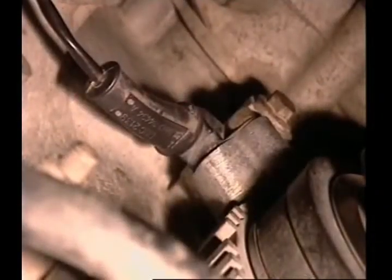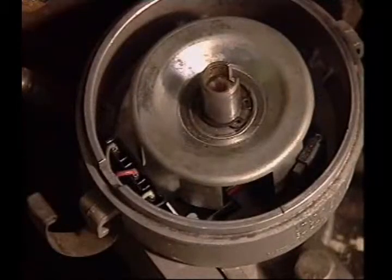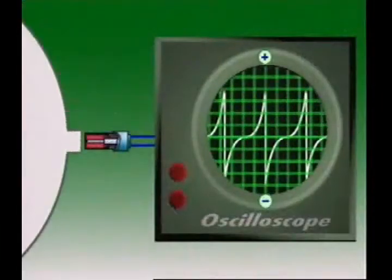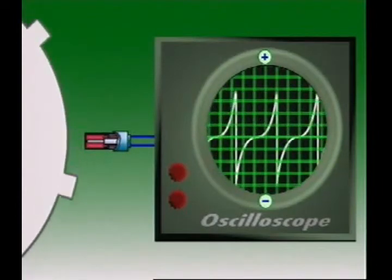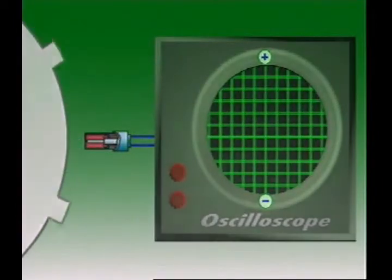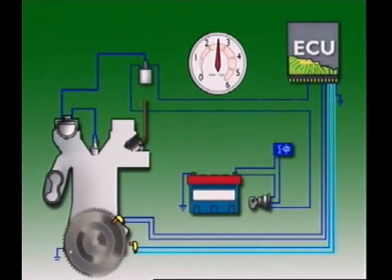The position sensor may be mounted externally on the crankcase wall, or it may be inside the housing of the ignition distributor. Inductive type sensors act as a small alternator and generate a sine wave, alternating current voltage. The teeth on the flywheel ring gear can be used to induce the voltage in the sensor, inducing 1 pulse per tooth. The frequency of the pulse allows the control unit to detect engine speed, or RPM.